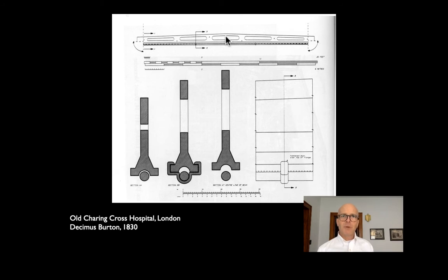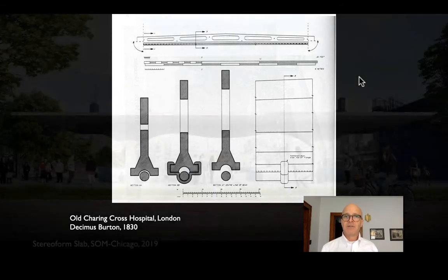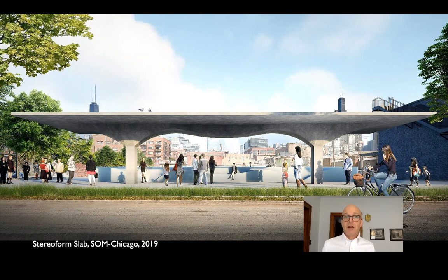Well, what I want to focus on for the moment is that fish belly shape, knowing that if you want to fine-tune a beam longitudinally, you can save weight by making the beam deeper in the middle and thinner at the ends, right? Tuning the longitudinal shape to the actual moment stresses that are within the beam itself. Now, today we don't often see this in steel because we typically roll steel, and we can't get the kind of sectional variation that you could if you were casting every beam. It's much cheaper to roll steel. Steel is a much better material for structural design than cast iron. So we live with that.